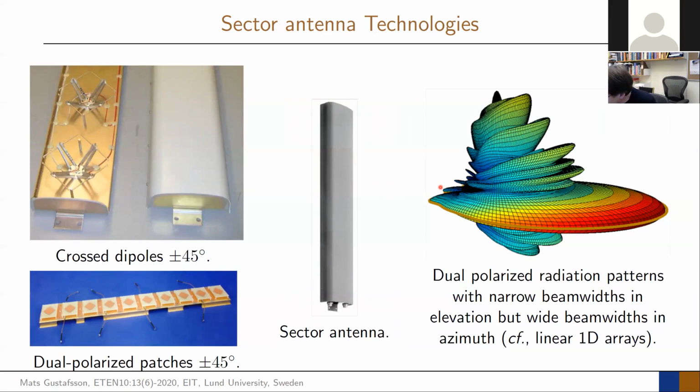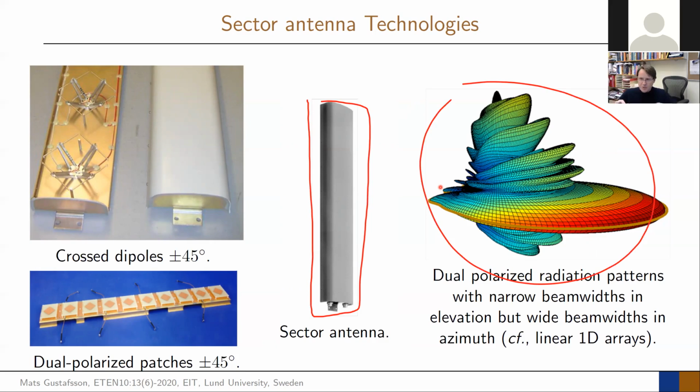So these are sector antennas, and the typical radiation pattern is what you see there. You can see that on the elevation side, it's quite narrow, so you really have a main radiation here. That is because the majority of your users are on the ground. You don't have so many users flying up in space, so you don't need to send your radiation up there. But they are distributed inside of this region, so you have some angle that this base station covers.